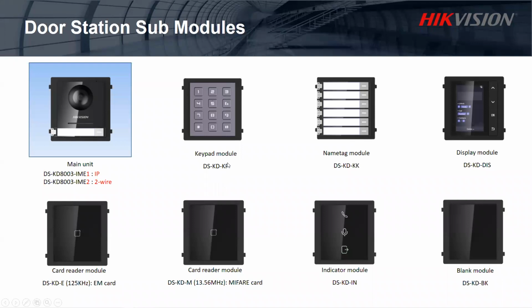Then you're going to see that we have multiple sub-modules. Depending on your application, you will choose which sub-module you require. As you can see here, we have the keypad input and the display module to dial the end user or to dial the room station. And here you have the name tag module, plus as well, we have two card reader modules. One you can use if you have third party or EM cards, to add cards to be read at 125 kilohertz. Otherwise, if you have MIFARE cards, then you can use the second card reader here.